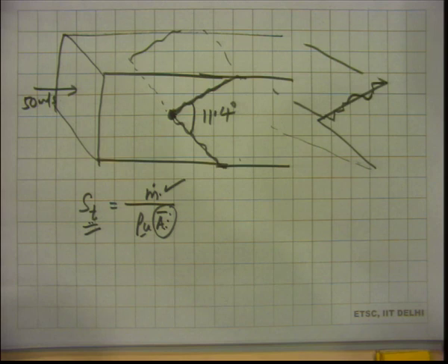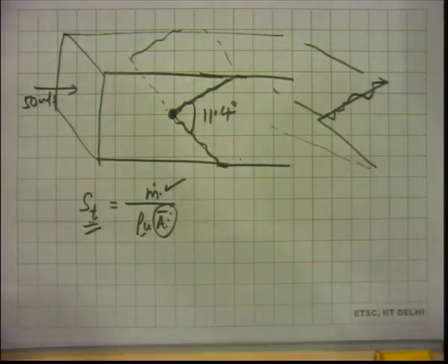Okay, and there are various ways of stabilizing these flames, turbulent premix flames. So this is just one example. This is called a bluff body stabilization. Now a rod is a bluff body, isn't it? So we are going back to fluid mechanics, right? It's not a streamlined body. A rod is not a streamlined body. Okay. And if you place a bluff body like this, then it sets up a recirculation pattern just ahead of it. Okay. So around this region, it sets up a recirculation pattern.